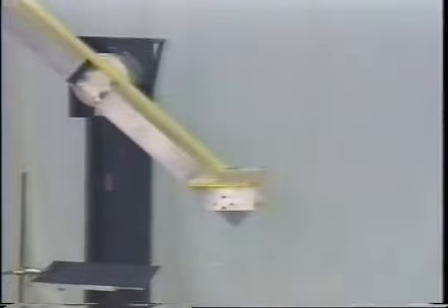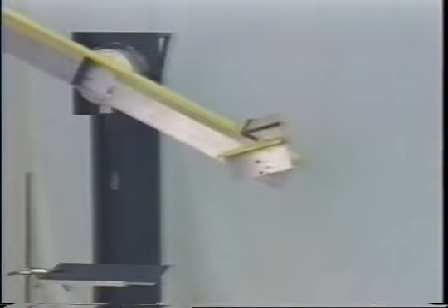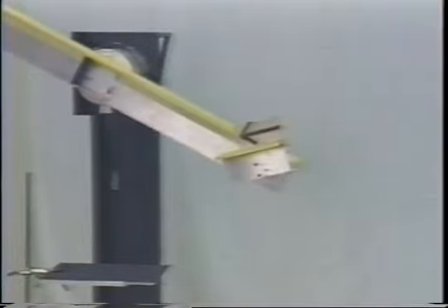Here the arm snatches a block from a table without using a gripper by accelerating into it. If we slow the planned trajectory to 2/3 speed, or increase it to 3/2 speed, the snatch fails. Here we reorient the part on the arm by throwing and catching. In this example, the robot first snatches the block and then reorients it by throwing and catching.